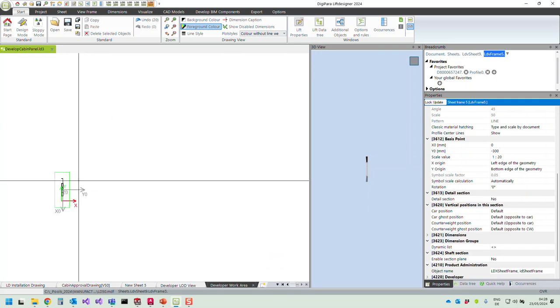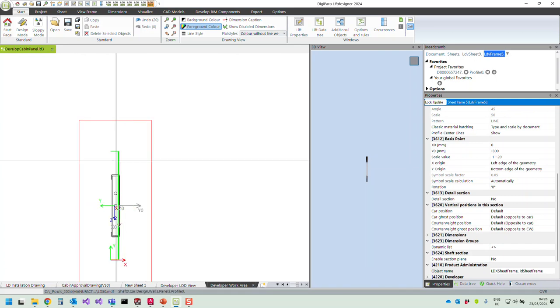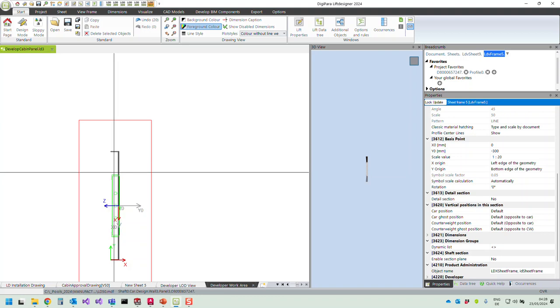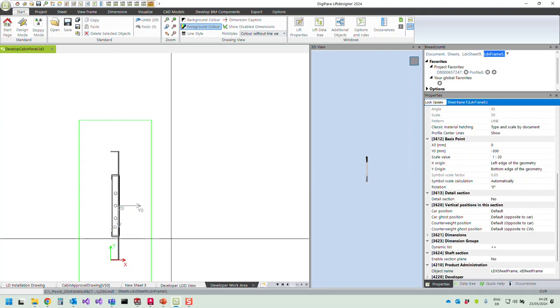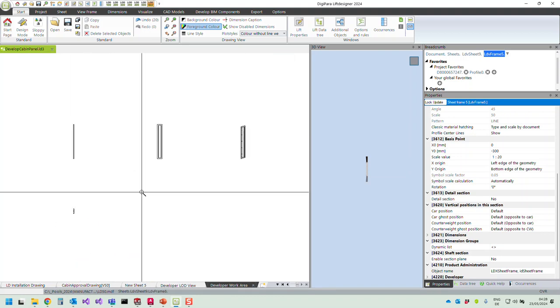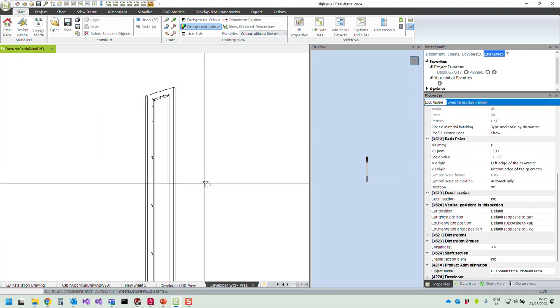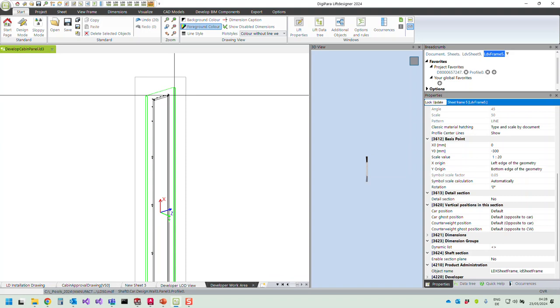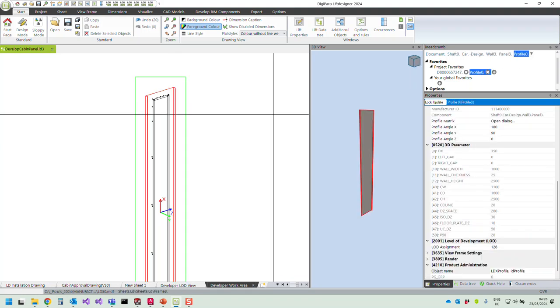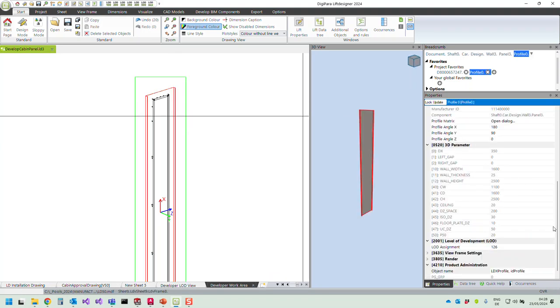Now in the developer area we see both parts, the standard component geometry plus the CAD model. Next, I will also change the standard lift designer profiles. I also have to change the LOD assignment, which we want to see in LOD 100, 200, 300, 350.